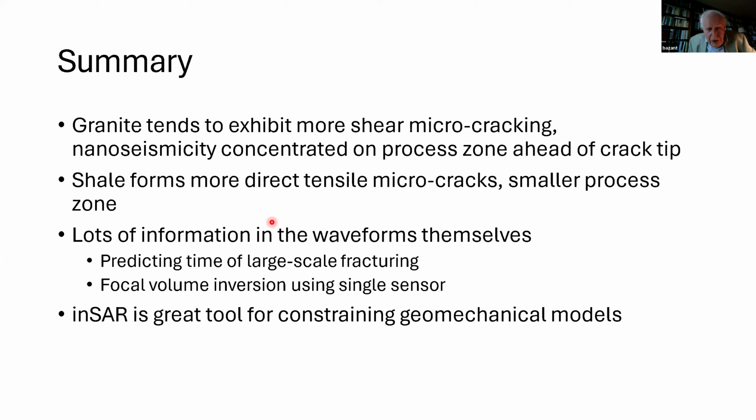In concrete, for example, fracture energy doubles if the compression is half of the strength, but it can go to near zero if it approaches the compression strength. And this was verified for other materials too, for fiber-reinforced concrete. So I think that's something that needs to be added. The test is quite simple, and I think it will be very interesting to see what's happening in shale. And there will absolutely be a big difference from granite too.